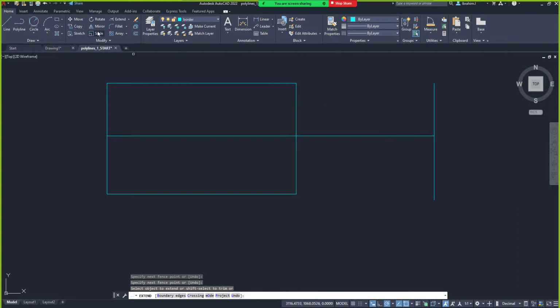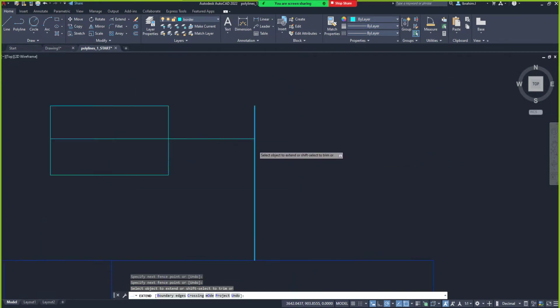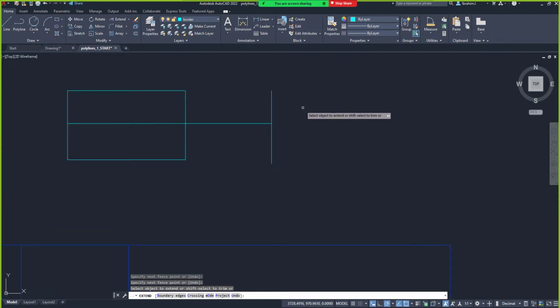Yes, I understand. If I go ahead to use the lengthening that we used the other time, did you have any extension point in front of it? No. All we just did was we selected the line we wanted to work on, we selected dynamic, and then we moved our line to the angle we wanted. The line was just moving with us, with the crosshair. Is it making sense? Yes.